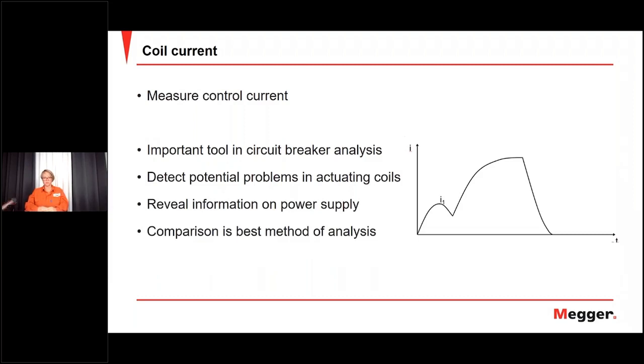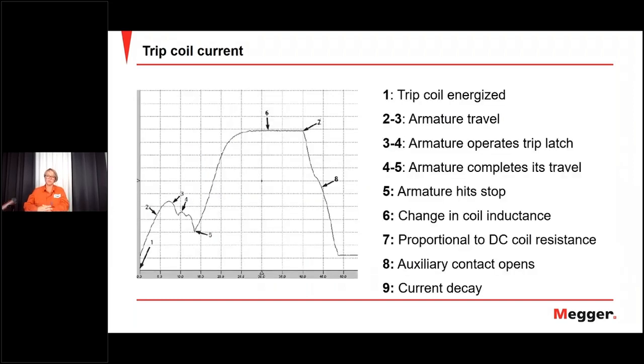And the best thing you could do here when you start is to work with comparison. Compare with similar circuit breakers, the same circuit breakers, the actual same unit, and make sure the whole graph is the same. Here we have somebody who looked at this in detail. That's one of my colleagues who used to work in Canada, and he really went through this in detail.